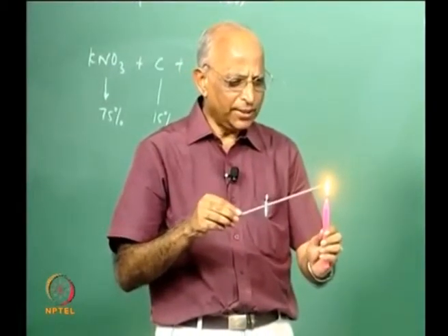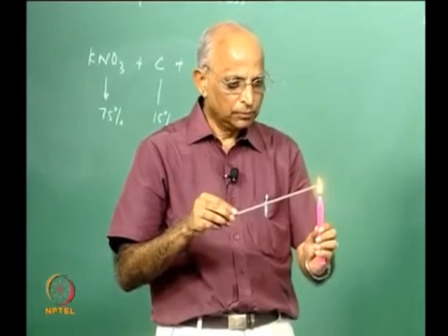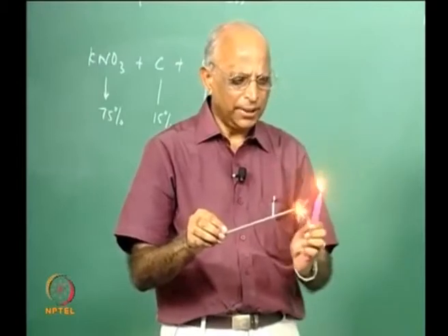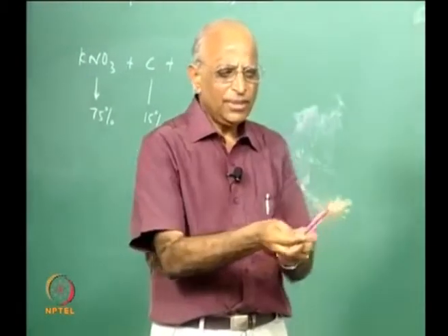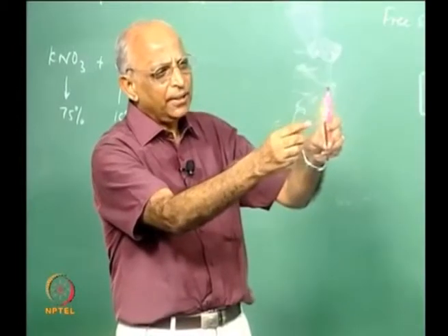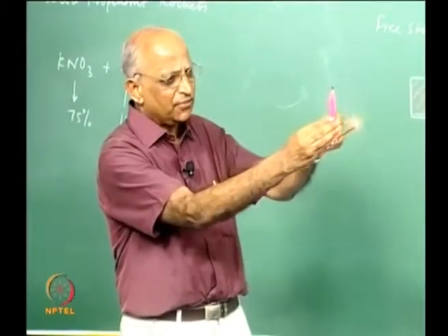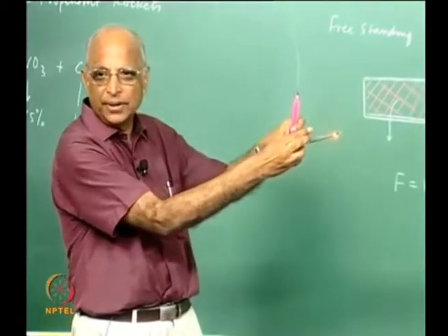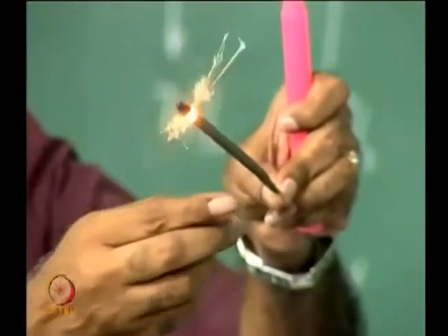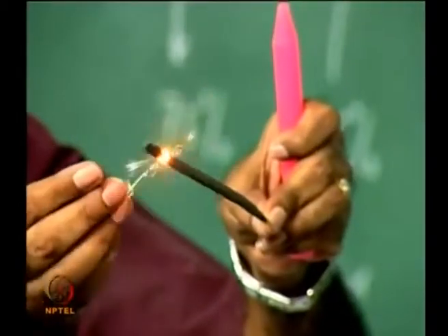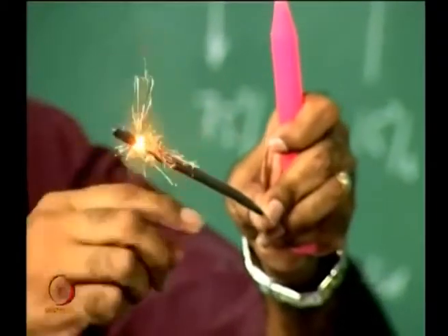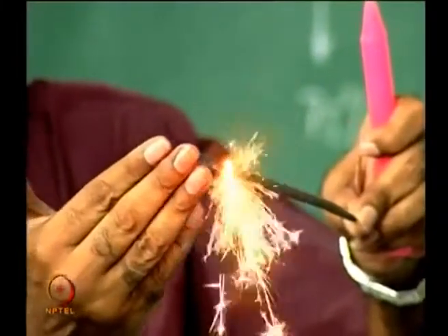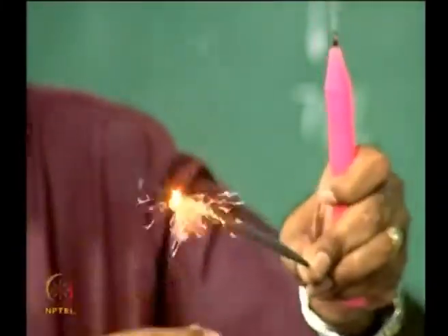Well, you ignite it at the surface. See, how does burning take place? You have the surface which gets ignited, and this ignited surface burns the next surface and all that. Therefore, you find that the surface is regressing at a particular rate. In this case the whole surface is exposed, but because it is air over here, the flame expands, it is not able to ignite the surface. Therefore, the burning surface area is perpendicular to this plane and the burning progresses. This is the case of this composition.